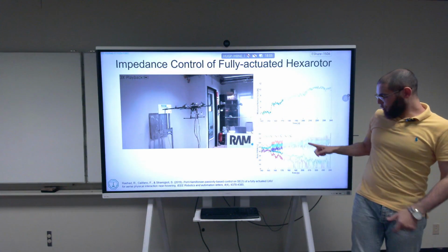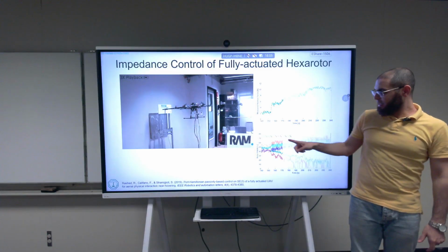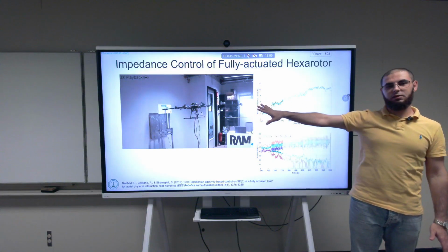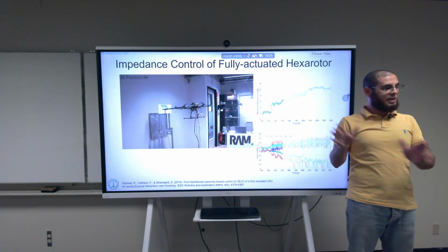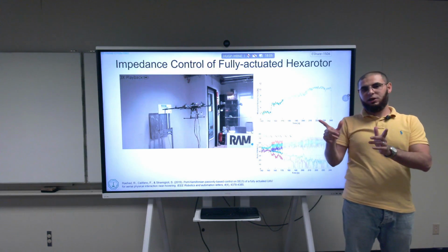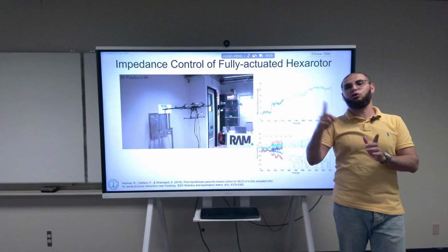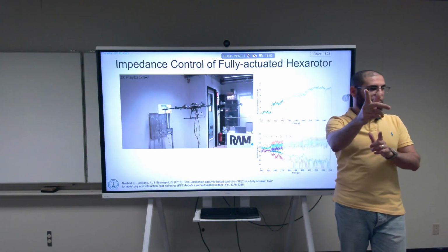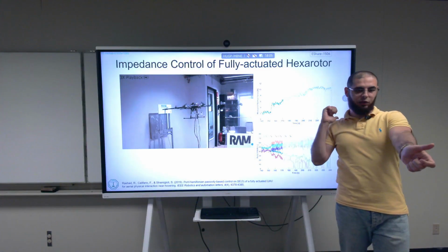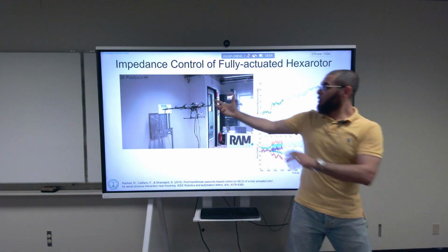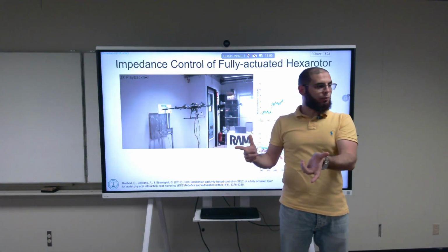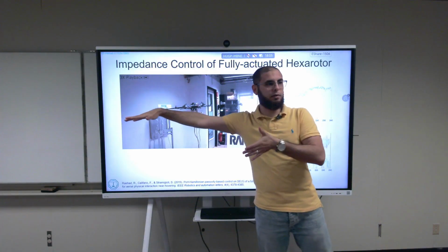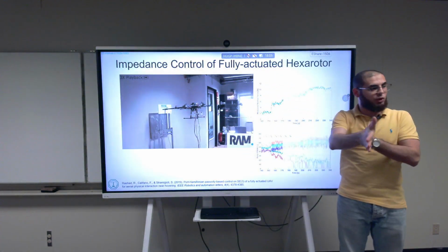What you're going to be seeing down here are the individual PWMs for the rotors. These are propellers that can rotate only in one direction, which means that they can produce thrust only in one direction. They cannot produce negative thrust. From the configuration of these propellers, when we ask it to push more, at some point two of the propellers will actually reach 0.